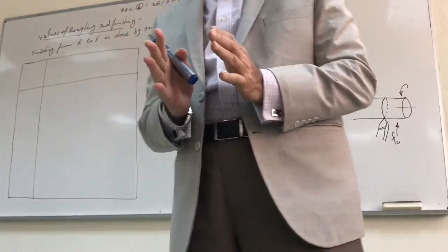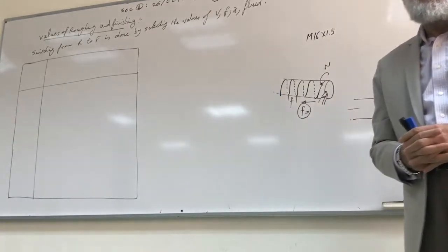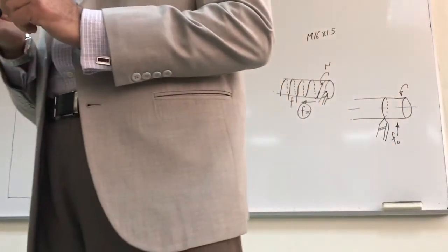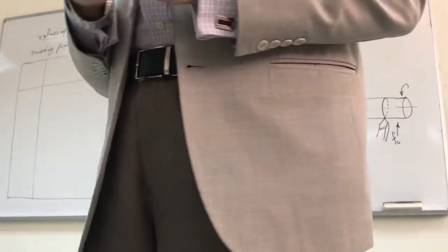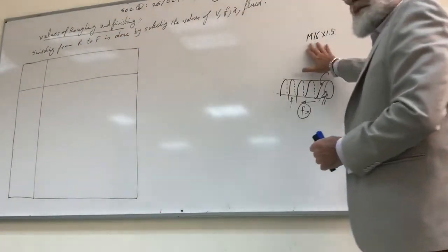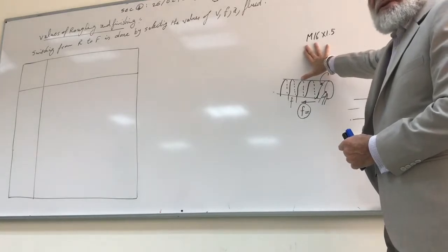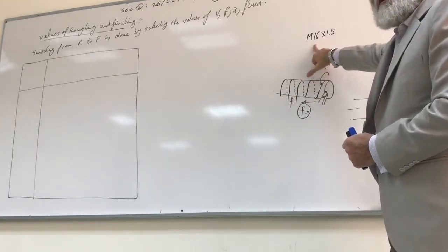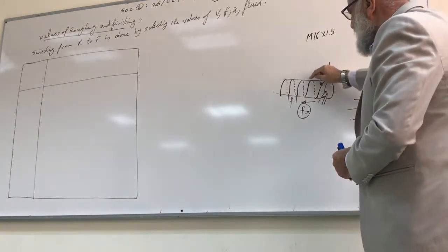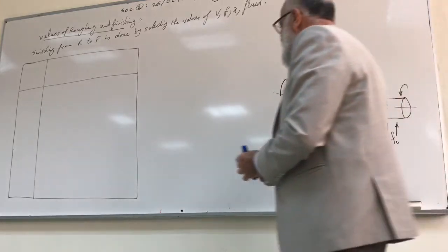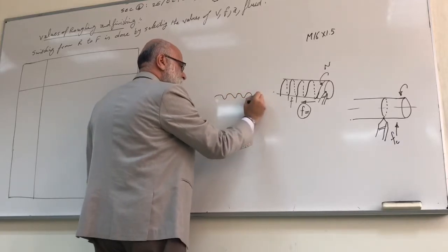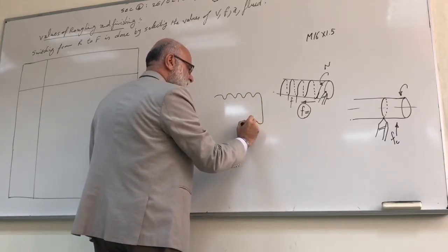The M is a suffix for metric, because we have a metric thread, British standard thread, Whitworth thread, square thread. We have too many types of threads, and this one of them is the metric thread. Okay? So the M means it is a metric thread. What does 16 mean? Outside diameter. Because every thread is a groove. The thread is a groove this way. This information, to be honest, should be given in 110.